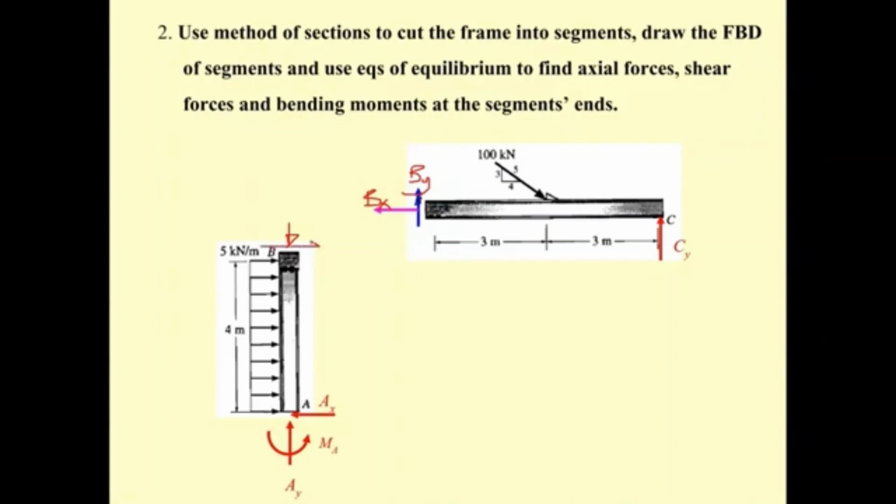Or if you are detailed in calculation, you may consider the joint here as the B joint, and then you may transfer the axial force here first, and then the shear here, by Newton's third law. This is to the left, this is to the right, this is up, this is down. You also get this axial force due to this shear force, and you will get this shear.